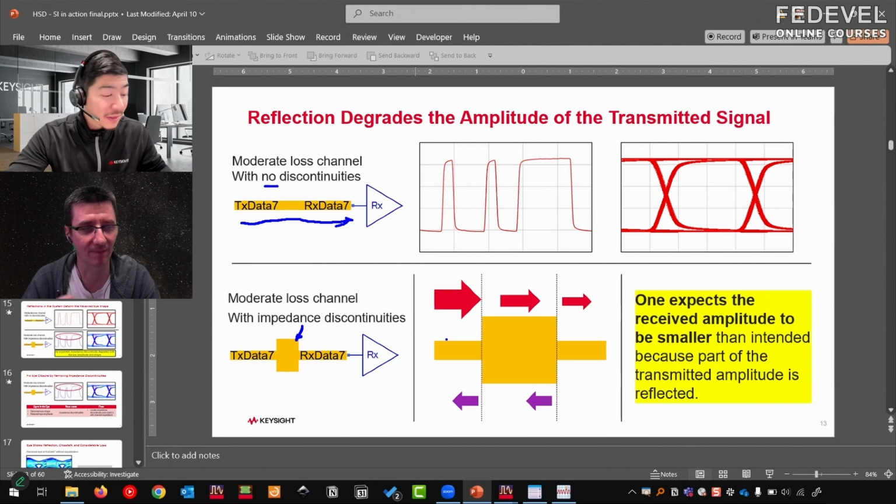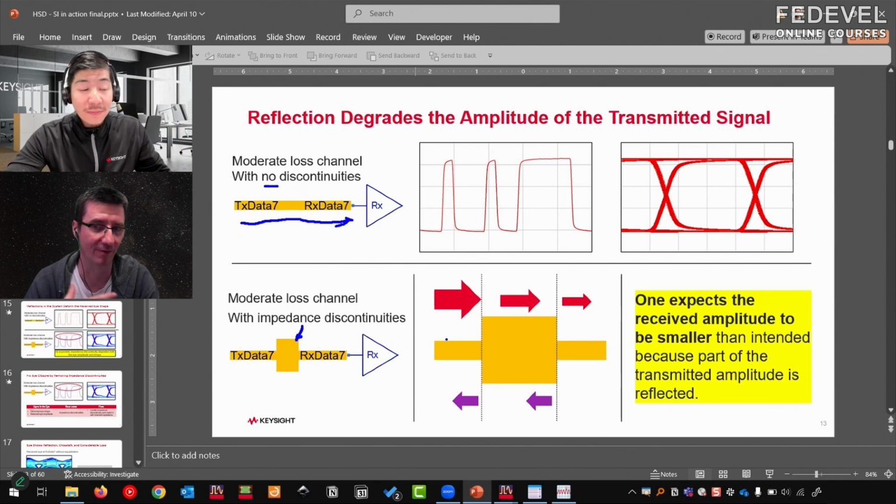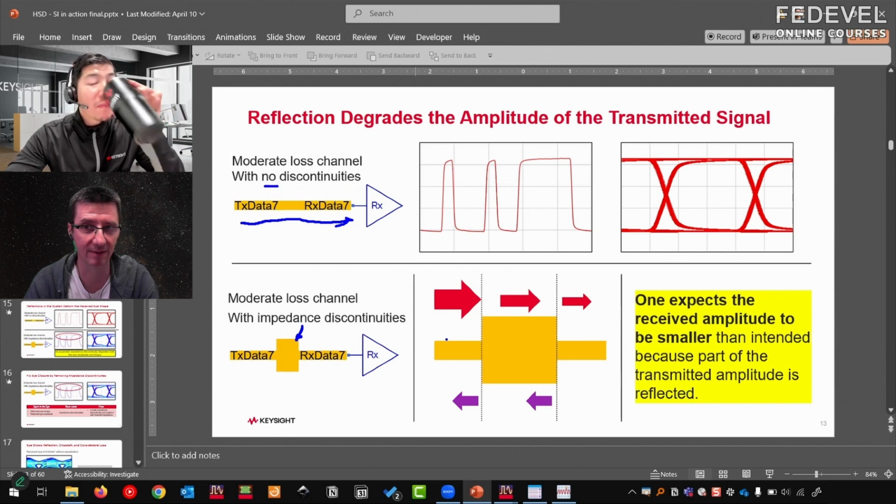This is only for illustration, but in reality it can be, for example, a via, because a via may have a different kind of impedance. Right, any type of impedance discontinuity can be modeled. That's a good point, this is more for demonstration, but you're right, Robert. It could be a via, a connector, a pad, a connection. Yes, a connector too.